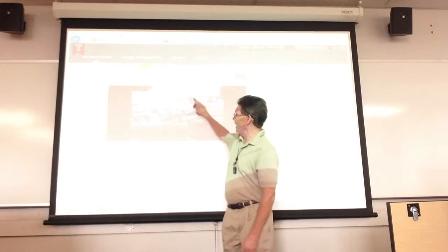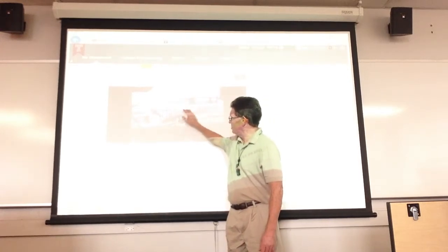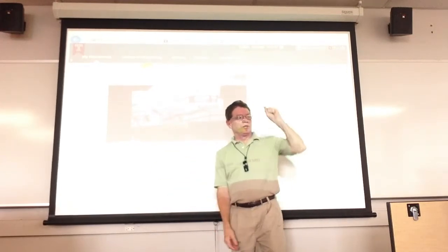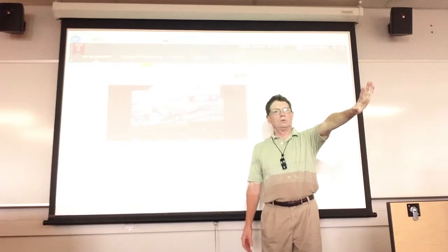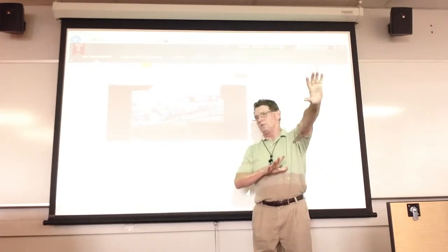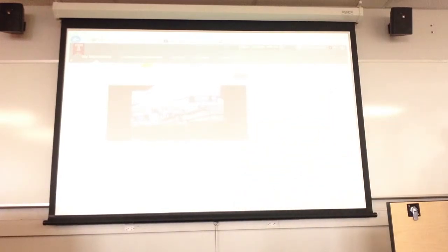Here's my port B right here. What I did was I took a whole bunch of LEDs. I put eight LEDs sitting on there. And all I'm doing is writing to the port, forcing it high, then forcing it low with a delay of 1 second. So I'm going high, low, high. That's all I'm doing, just writing to it. High, low, there.